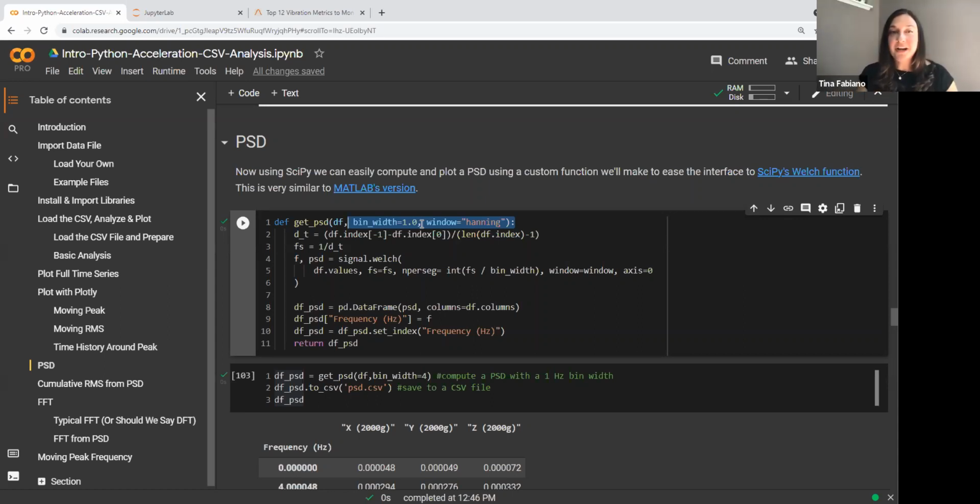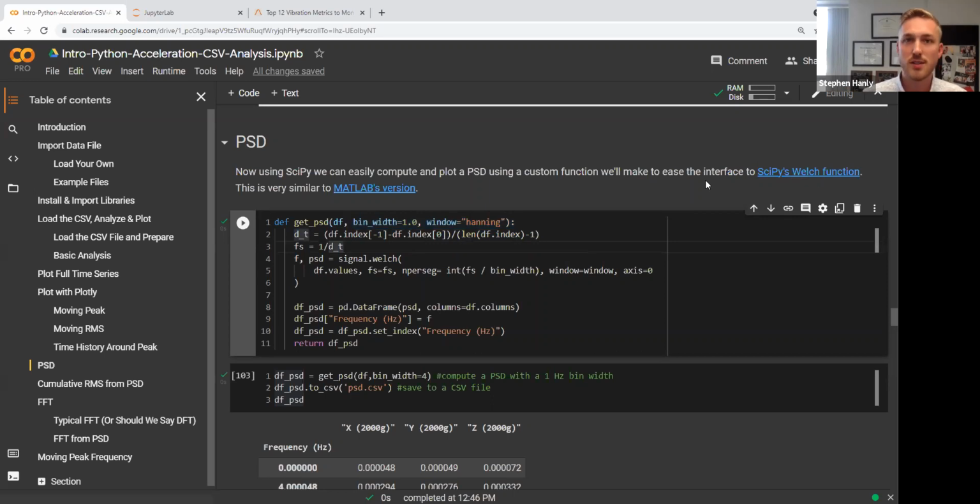Will this be useful for analyzing shock data from barge tests, et cetera? Yes, for sure. One of the things that is not very easy out of the gate is the shock response spectrum. For the power spectral density, there's a built-in function in SciPy, but there's no built-in function for doing a shock response spectrum. So now in the enDAQ.calc library, you'll be able to pass it shock data or acceleration data, and get a shock response spectrum.